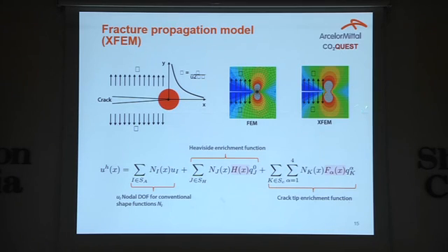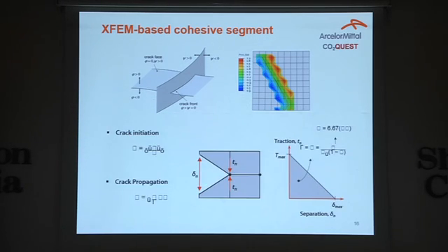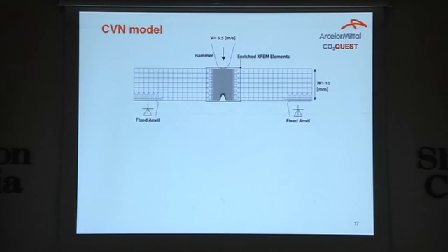So we use the XFEM approach, in which we add two extra functions to the finite element method, the Heaviside functions and crack tip functions, to capture singularity and separate the crack. More explanation is beyond the scope of this presentation. Again, we use the sine function to detect the crack, and then we use the cohesive approach to model the crack behavior. Let's say we have two variables, which are the cohesive parameters: the separation occurs and the damage accumulation occurs over time.